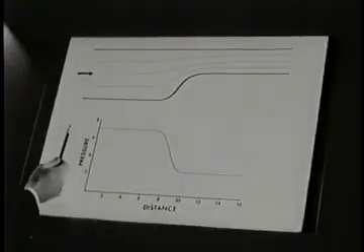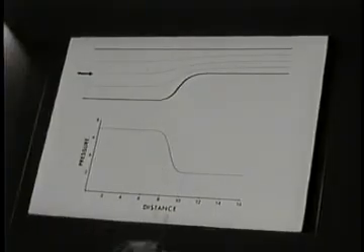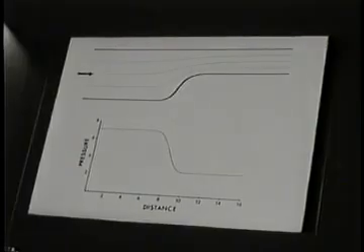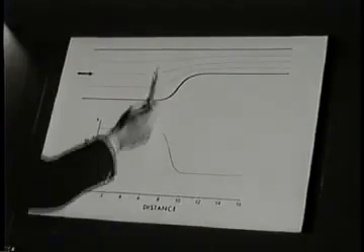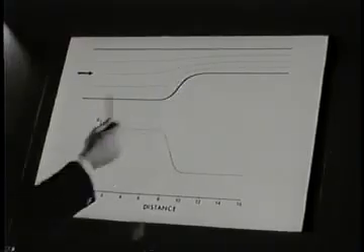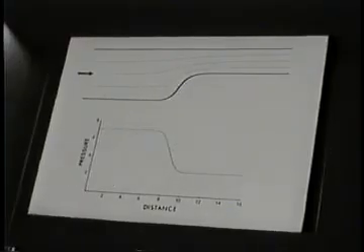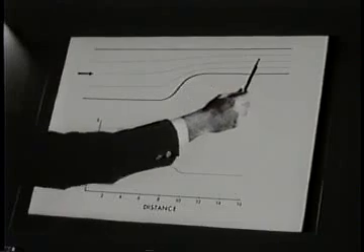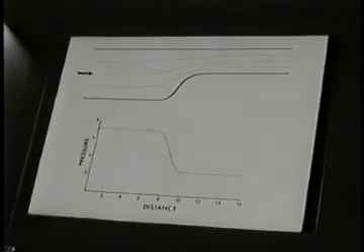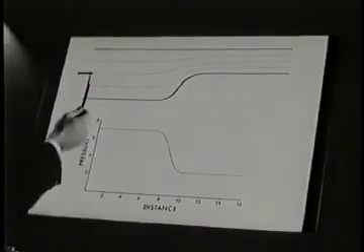Far upstream and far downstream, where the streamlines have no curvature, the pressure will be uniform over the two cross-sections. From the shape of the channel, we may expect that the streamlines will be of this general shape: concave up in this region, concave down in this region.